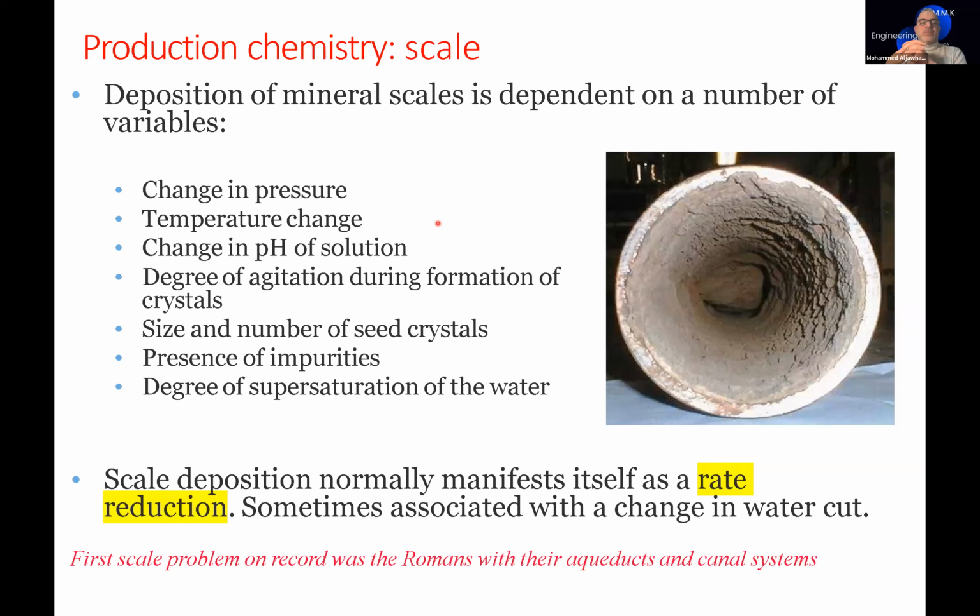The size and number of these crystals may be big enough to deposit inside the wellbore or the reservoir or the facilities. Impurities, for example, have we seen the illustration before? When we have very close injectors, and the water injected inside those injectors is not fine enough, there are a lot of impurities inside it, and we can see it on the other hand, at the end in the produced wells.